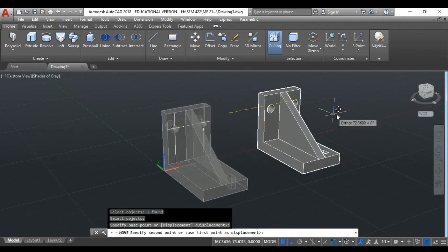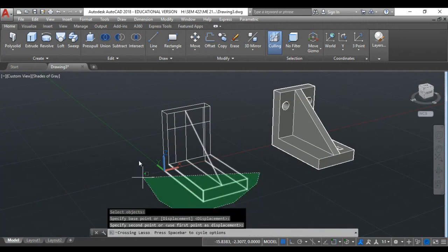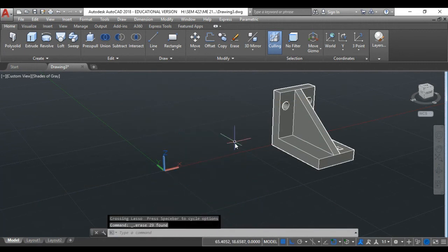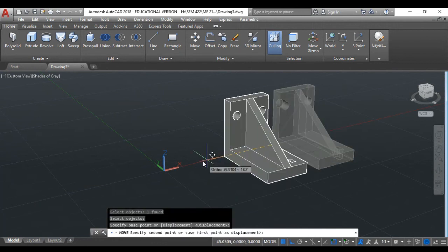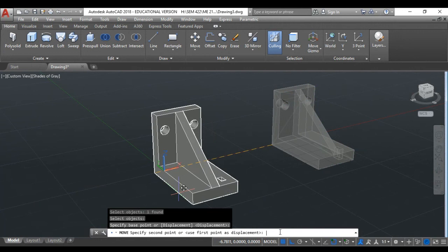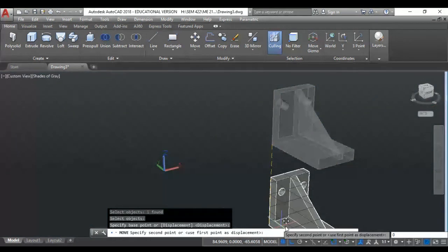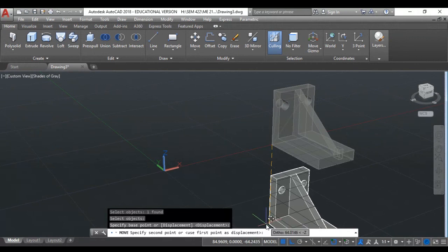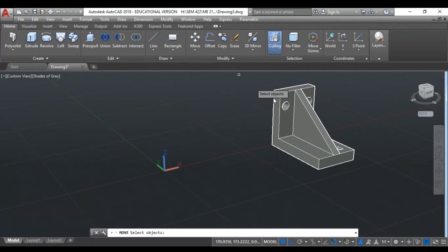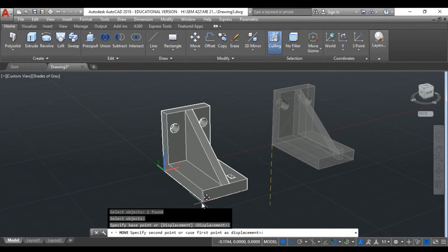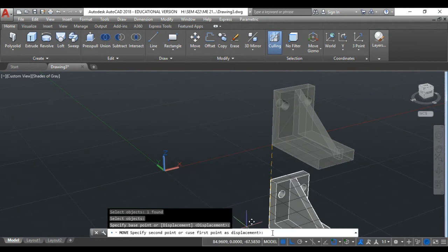Now it's time to go and say move that object from where it is to any other location, and then finally take everything and remove it, and then bring it back, move again the object. This time I'm gonna move this corner to the location 0 0 0. So simply write down 0 comma, okay, I'm sorry, escape guys, again move the object from that source all the way to that sink, second point 0 comma 0.